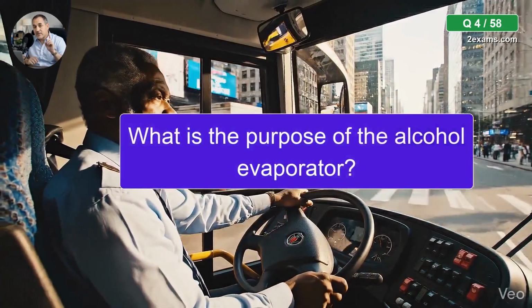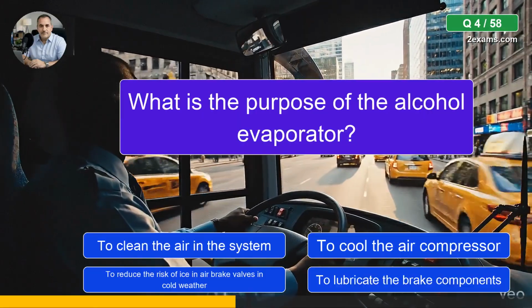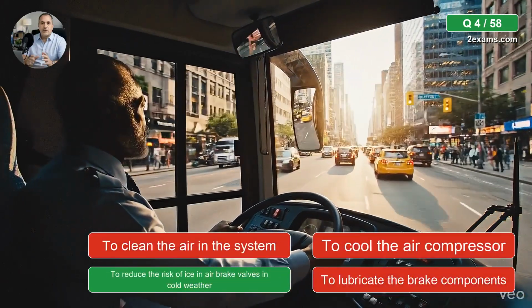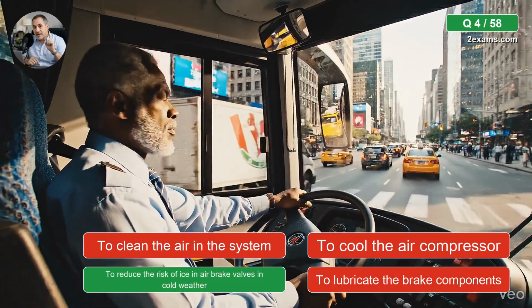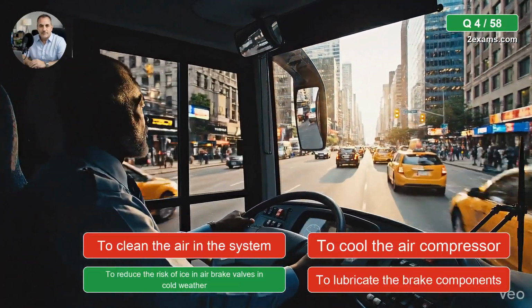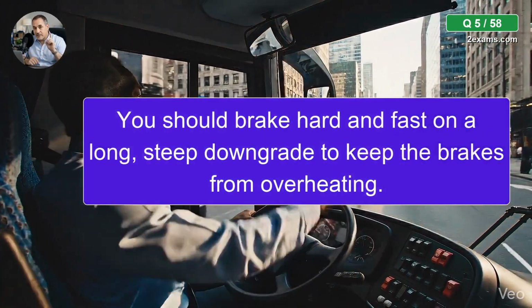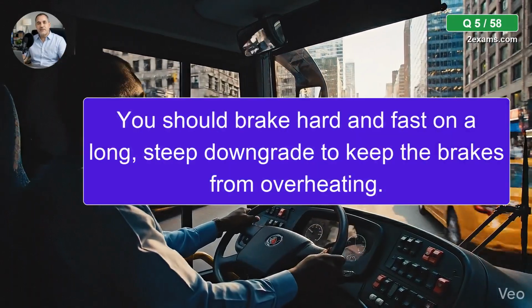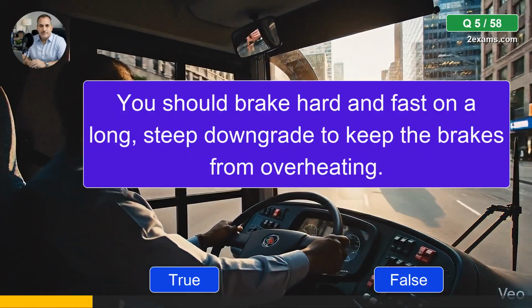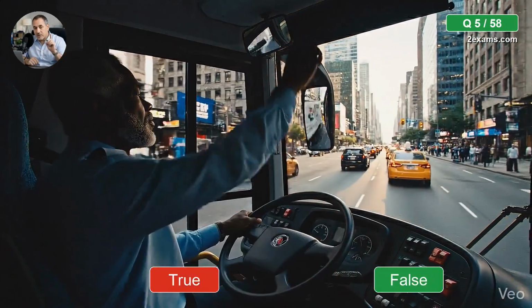What is the purpose of the alcohol evaporator? The correct answer is to reduce the risk of ice in air brake valves in cold weather. You should brake hard and fast on a long, steep downgrade to keep the brakes from overheating. The correct answer is false.